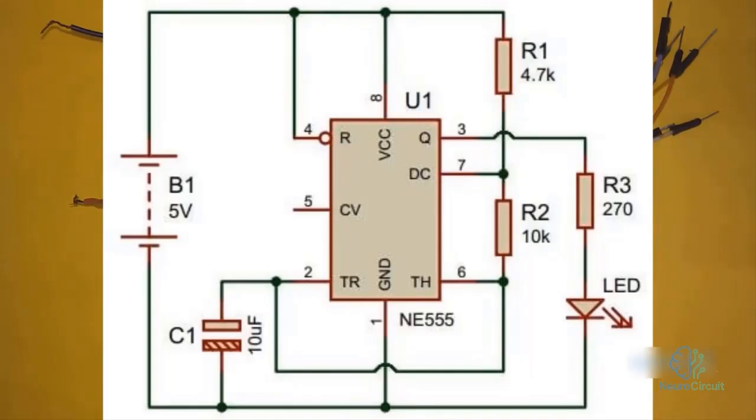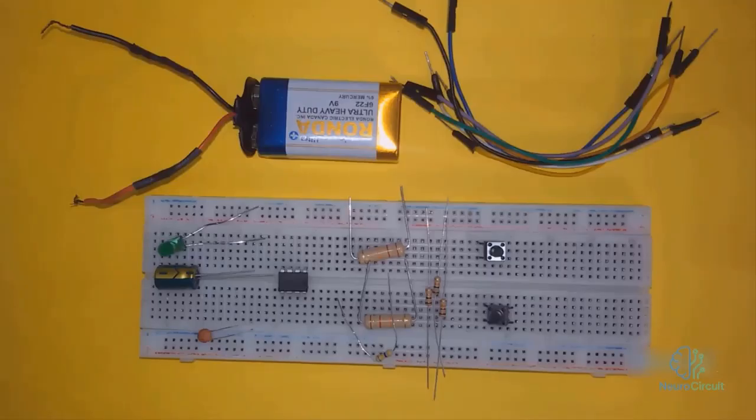And for each one, for example, if you need a 10 kilo-ohm resistor for this circuit, it's good to have two. Preferably, have one extra of each component that's introduced, so if one is faulty, you can use the other. A 270 ohm resistor is also needed according to this circuit, and of course, jumper wires are an inseparable part of working with a breadboard, and you'll also need a 555 IC. So these are the components we need for the astable circuit.